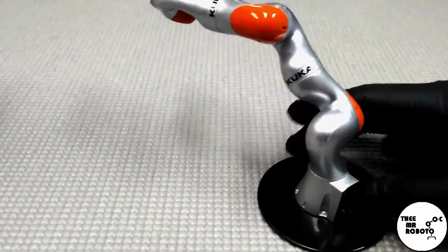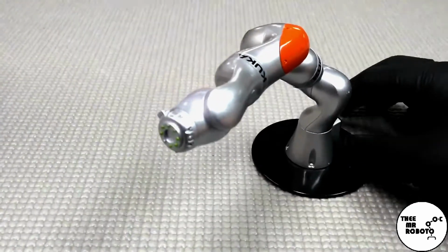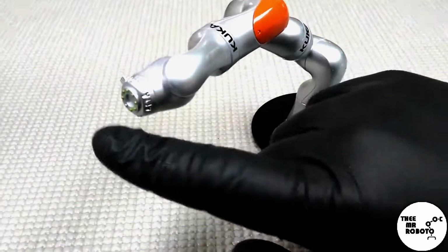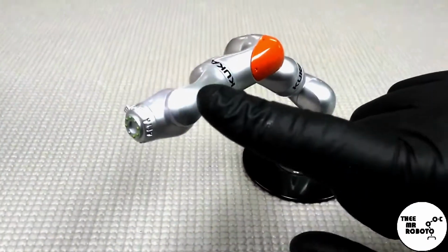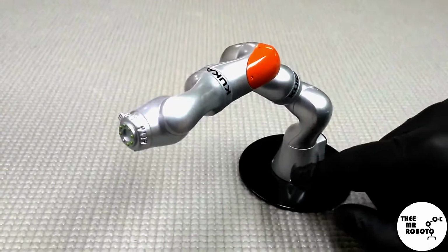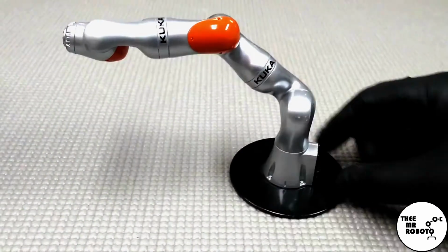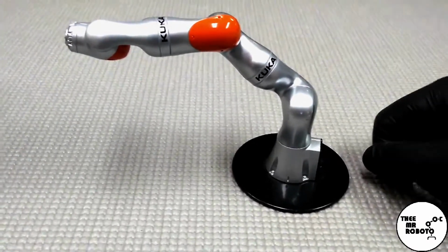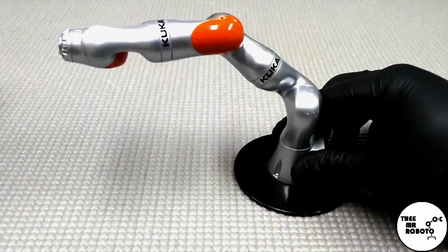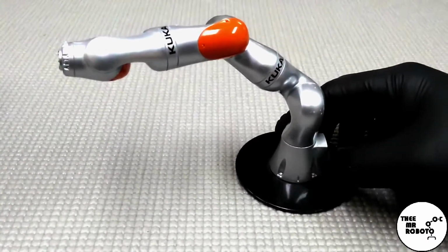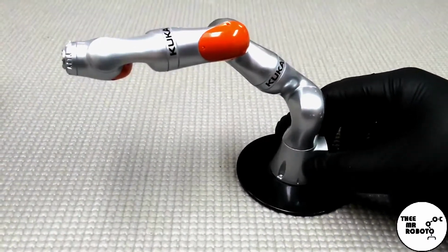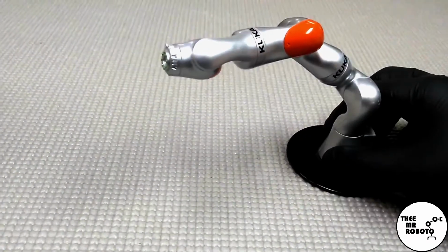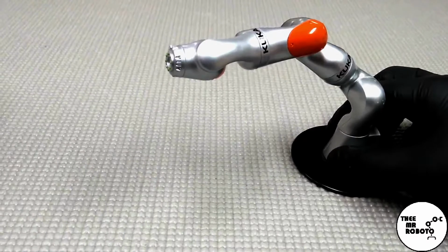So these are the native coordinate systems, all right? These can't be changed. This one is always there, and it's based on the geometry of the robot arm. Okay, this one is always here. It's always the base of the robot or somewhere in close proximity to the base. Okay, so the next type of coordinate system is a coordinate system that's based on the tool that you're using.